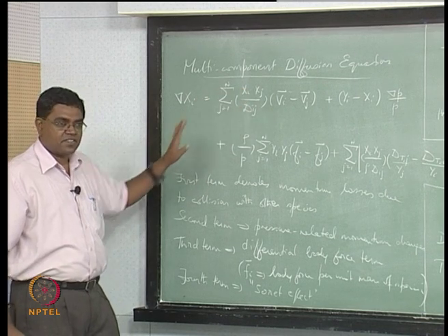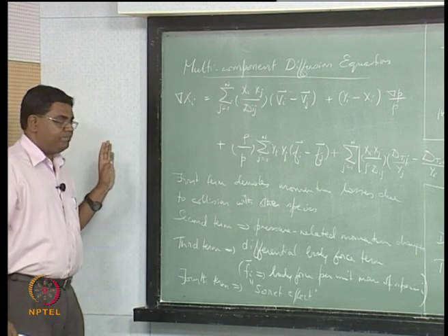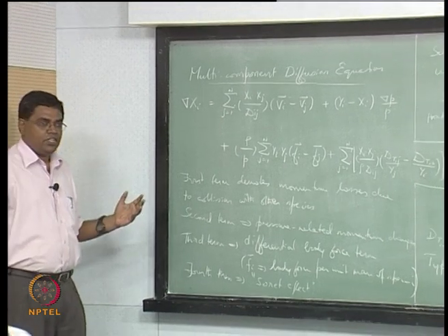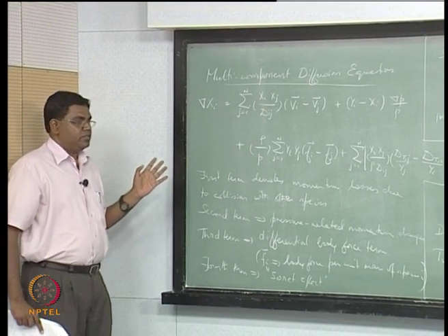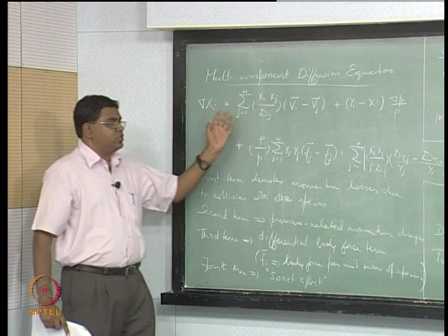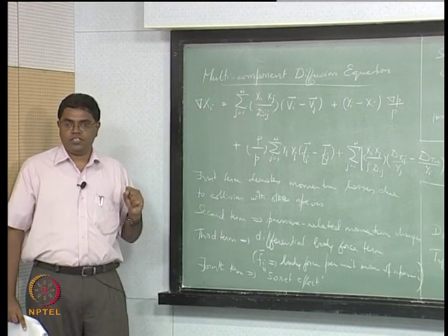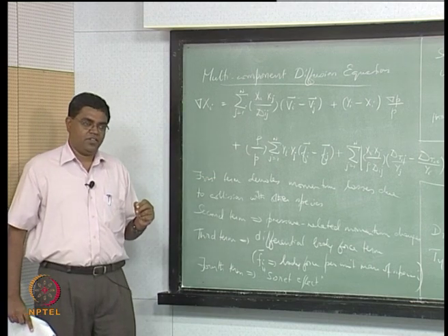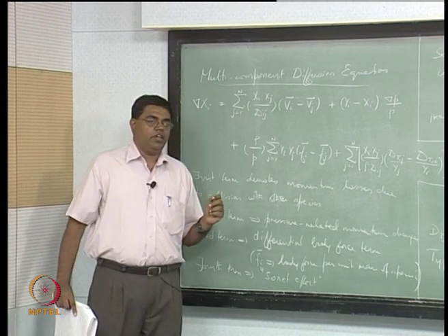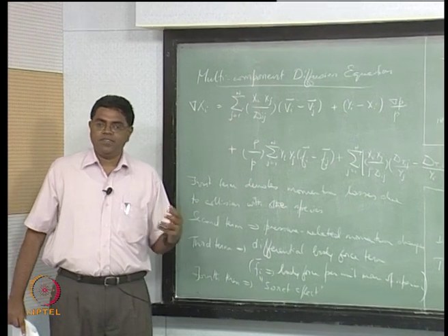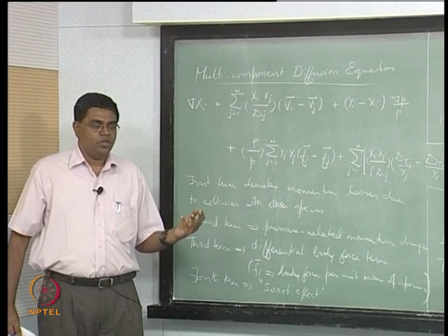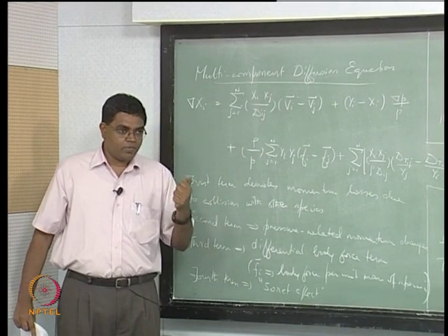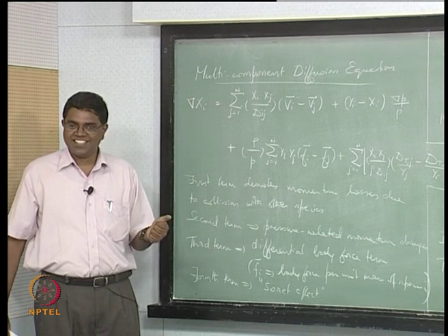Alright, this is a little bit indirect, because we would like to think of a diffusion coefficient that is a function of only one species at a time. We don't want this pairs of species business, because when you think about a thermal conductivity or a specific heat or something of that sort, we can easily think of those as being properties of only one particular species.